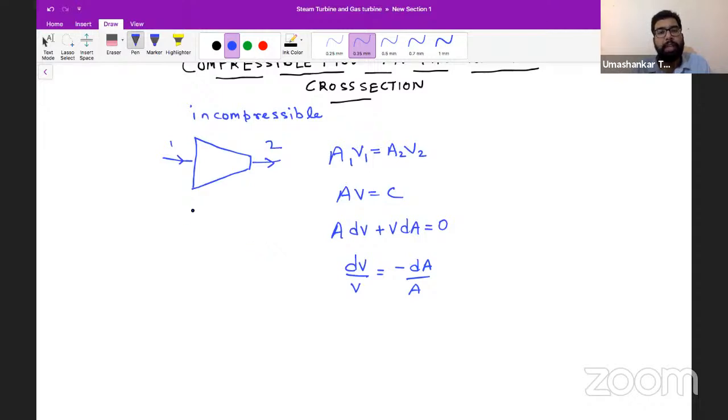Right? So if I say in this, what is a nozzle? In the previous lecture, I have defined what is the nozzle. So nozzle is something in which the velocity increases, means you have to design a passage. Now, listen to me very, very carefully. We have to design a passage in which the design should be like that, that during the flow, the velocity of fluid increases, and during the flow, the pressure of fluid decreases. Then only you can name it nozzle. Otherwise, you can't name it nozzle.